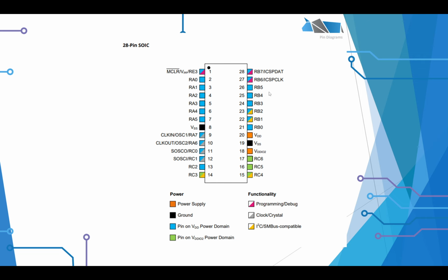Actually, I should have mentioned this. What was that red wire doing? And I'm going to have to bring this up, because this is the domain issue that people are going to have to learn very quickly. This is the VDD for the overall chip. This is the VDD IO2 for the data domain, this green domain. So the way to think of these is that that is a voltage domain.